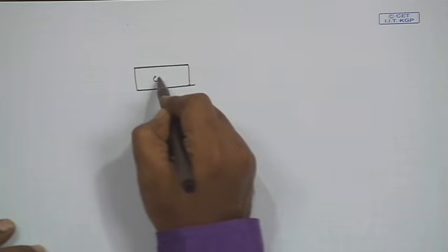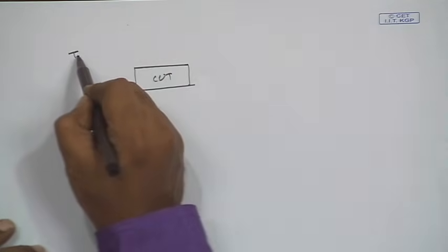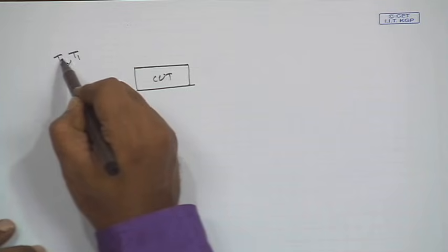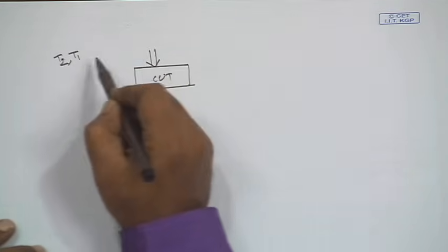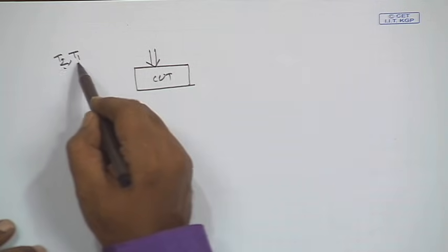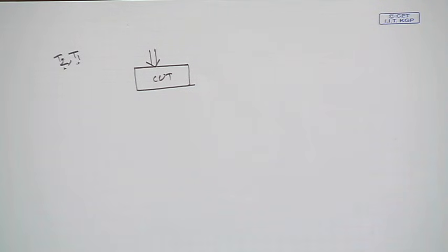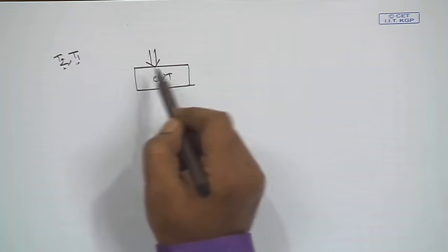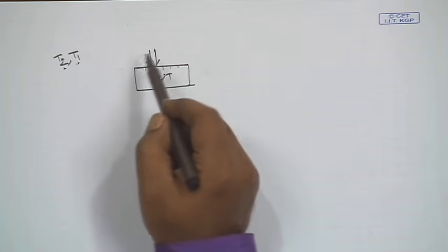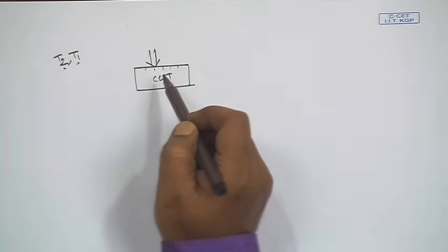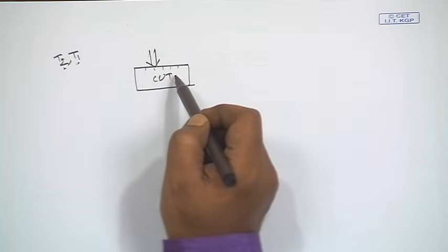What I mean is, if this is the circuit, this test pattern generator has given me two test vectors, say T1 and T2. First T1 will be applied to the circuit and then T2 will be applied to the circuit. Now, if we can ensure that between T1 and T2 many bits are not changing, then many of the gates which are getting input from the primary input will not do a transition, and subsequently the gates at successive stages will also not make much transition if the first level gates are not doing transition.